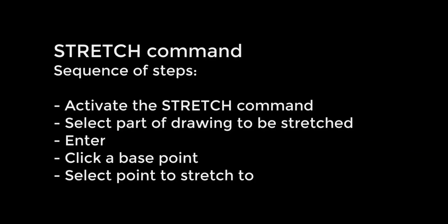Okay, in this video we're going to look at the stretch command. If you've drawn an object too long or too short, you can adjust the length of that to your desired length by using stretch. So the sequence of steps for this is clicking on stretch.